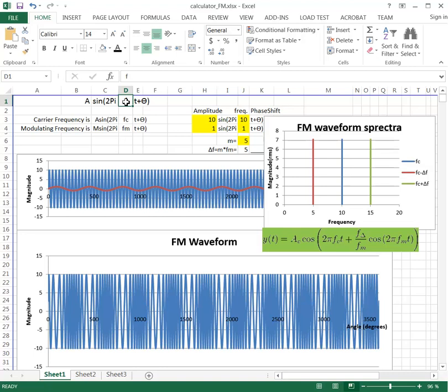The other thing that's quite interesting is the magnitude of the modulating frequency has no effect. We can see in here in the mathematical expression that there is no term in here for the magnitude of the modulating wave. It's simply not there. Here's the magnitude of the carrier wave. In this particular example, it's written as a cosine. It doesn't really matter. We've got the frequency of the carrier, the frequency of the modulation wave here, and this term here, delta F or F delta.